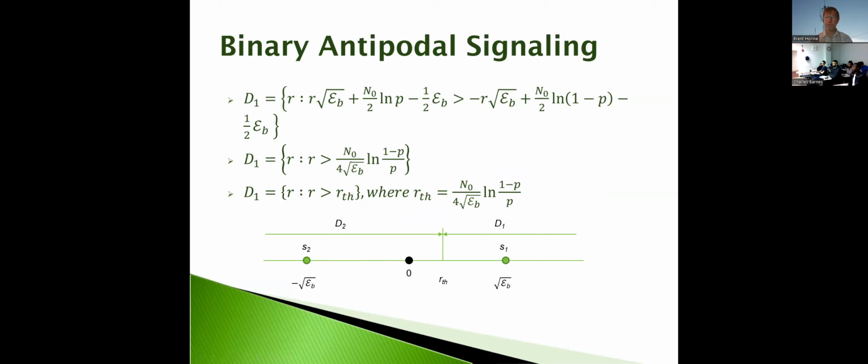So you're looking as an engineer and you're designing that waveform, and you're asking, am I dealing with a super high power system in a very benign environment? Let's say I've got Wi-Fi in my house. I've got to maybe go through a few walls, and that's going to impact my received signal power. But I'm plugging the access point into a wall so I can push out a fair amount of power.